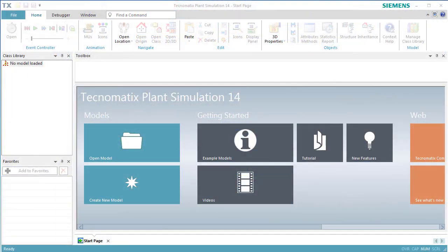This video demonstrates how to modify the built-in transfer behavior of a material flow object with an exit control. This control overrides the built-in exit strategy, meaning that we ourselves have to make sure that the part moves to the station of our choice. The material flow object activates the control as soon as a part is ready to move on after being processed.